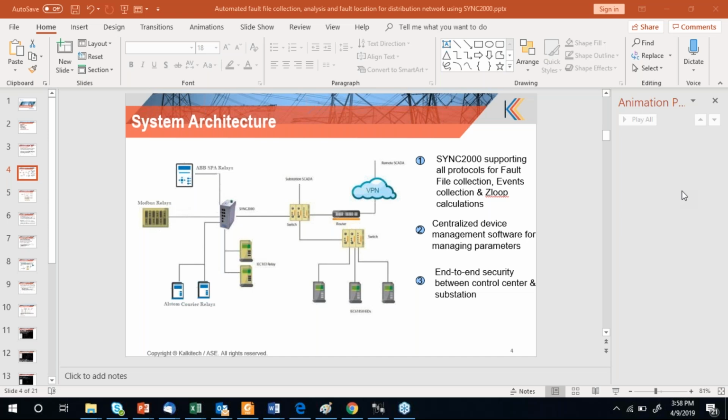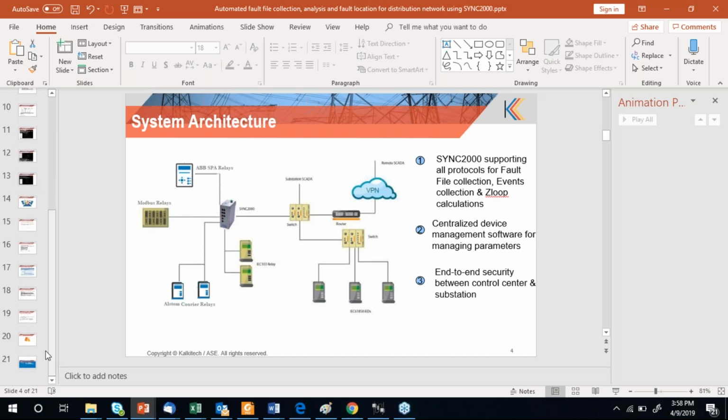The requirement is to collect it from the IEDs, then compare it with the master configuration file that is available, and whenever a change is detected from the available configuration file, we need to throw an alarm. So that we are now working out. We are successful in implementing it for Sel relays, and we are working out for other relays also. So automatic configuration file retrieval and making it automatically available to the databases of PSCS.